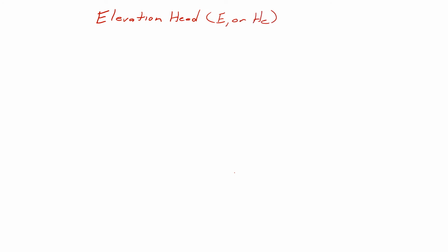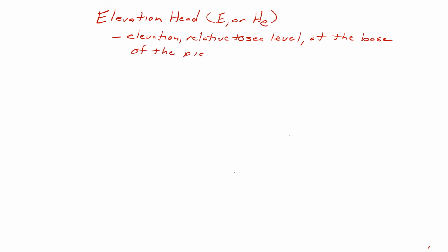The elevation head, sometimes it's referred to as E, or sometimes H sub E. This is the elevation relative to sea level at the base of the piezometer. And again, a piezometer is just a well with one opening at the bottom.